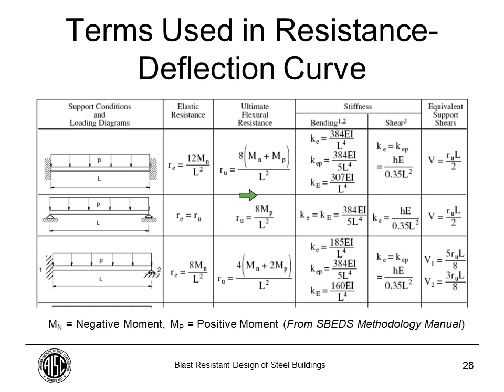Right here you can see the different stiffnesses for the different regions when you're in the elastic region, elastoplastic region, and finally the plastic region. And you can see the equations used to calculate your equivalent static loads at the ends.